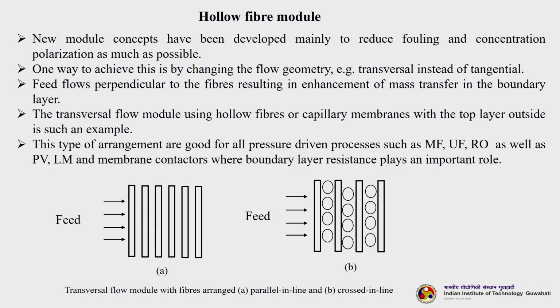Nowadays new module concepts have been developed mainly to reduce fouling and concentration polarization as much as possible, because the most important problem in membrane separation is concentration polarization and subsequent fouling. So, to reduce concentration polarization as well as minimize fouling, many new developments are coming every day. Membrane scientists are working toward better module design. One way to achieve this is by changing the flow geometry.